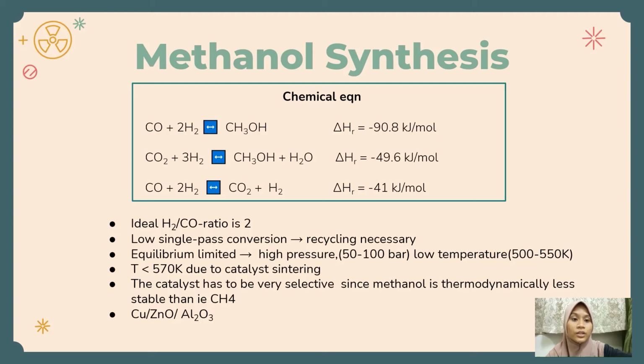It is equilibrium limited, as it is a high pressure process, which is 50 to 100 bar, with a lower temperature, around 500 to 550 Kelvin. The temperature for this process is below 570 Kelvin due to catalyst sintering.